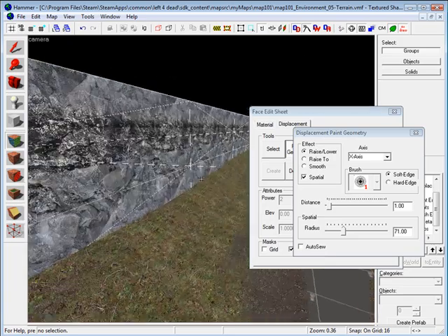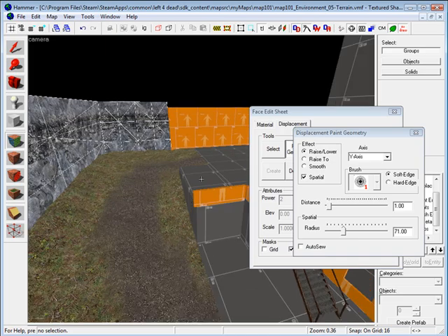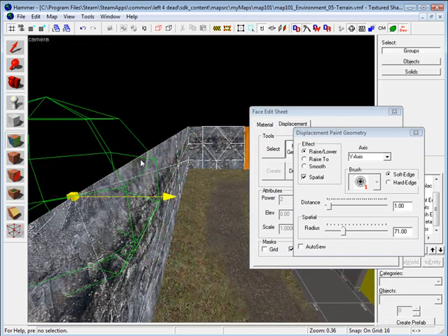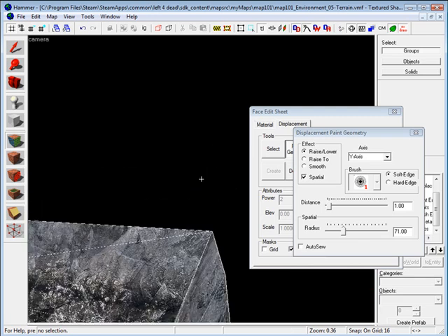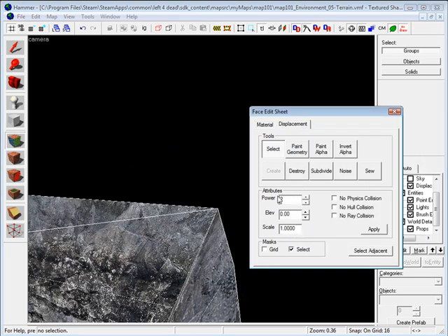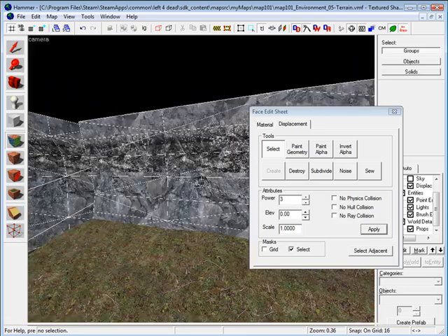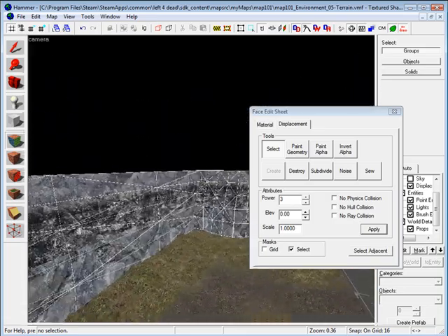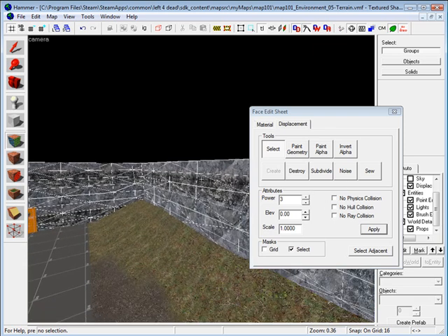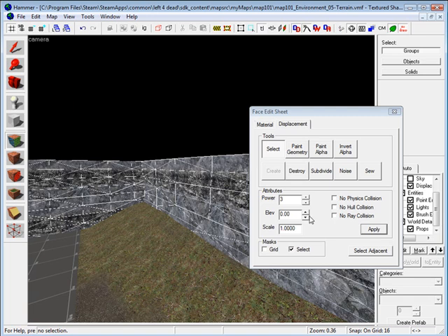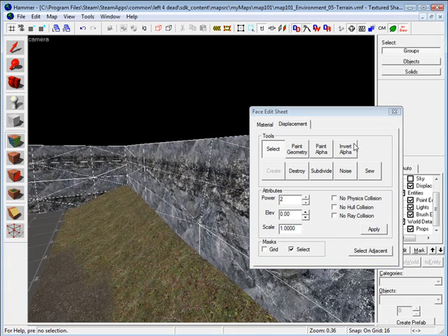And let me show you really quick. For this part, I'm just gonna switch it to y-axis. I'm gonna do the same thing. And if you need more control, you can always change your power attribute. You can bump it up to 3, apply, and it'll give you more control of how it's gonna look. So I'm gonna stick with 3 now. You want to start with the lowest number, shape how you want it to look, then you can always bump it up. That's kind of the workflow that you want to work with. Start with the lowest and then go higher.